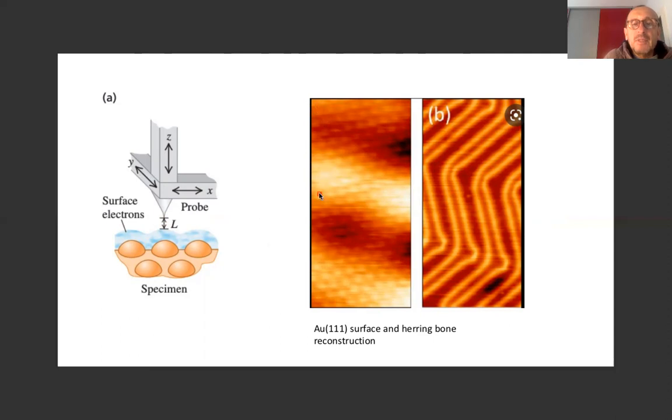So this image over here is built by swinging, let's say, the Y voltage in this direction, applying a little bit of a step and measuring in the other direction while swinging the voltage. So you apply these different steps in this direction and that direction, and you can sweep this region perfectly well by controlling the deformation of the piezoelectric material.